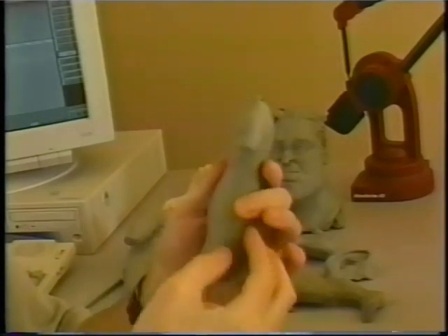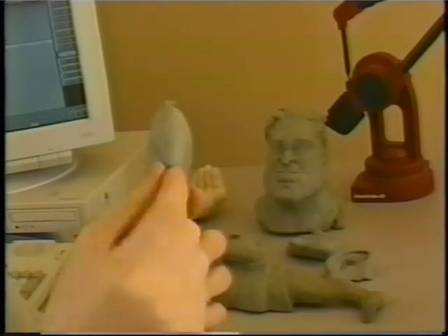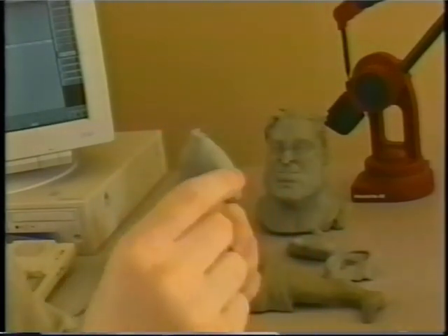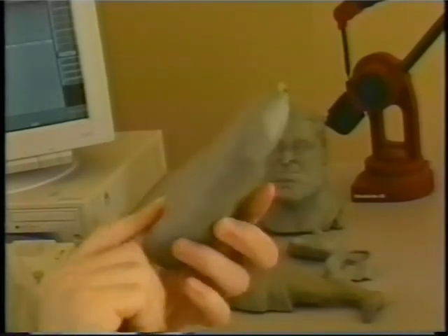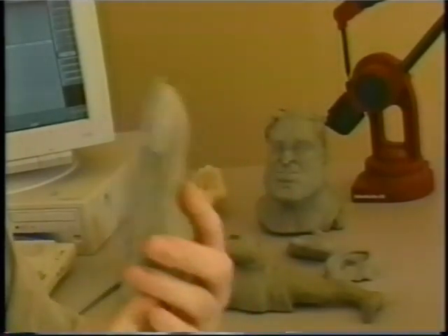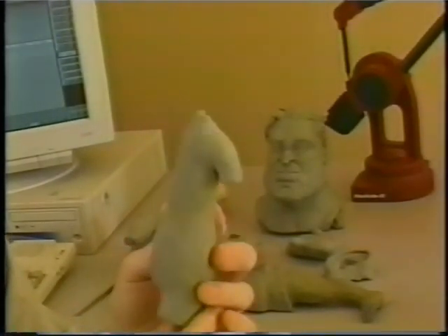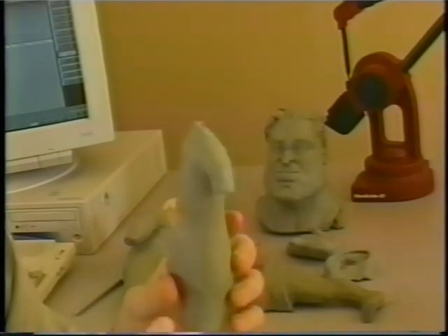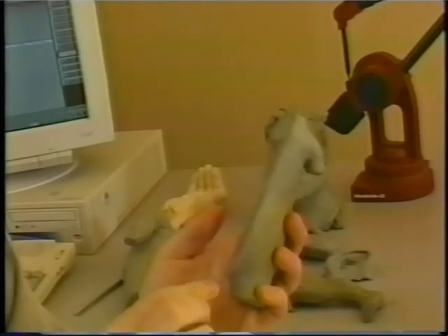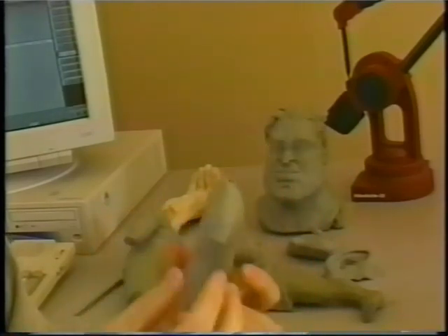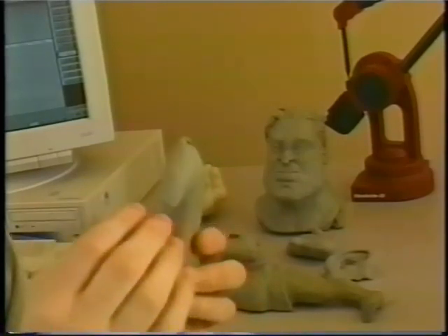Next we'll talk about this body, cartoon character body, and this is one of the trickier methods. You start at the wrist, or in this case right at the arm stub, and you wrap around the shoulder and then down the body and down the leg. So it's actually on one half of the body, one continuous spline from wrist to ankle, if you want to do it that way. And what you do is along this edge, and then the inside of the leg. So it's the inside of the leg and the outside of the arm. You close them by magneting extra points if it's B-splines.